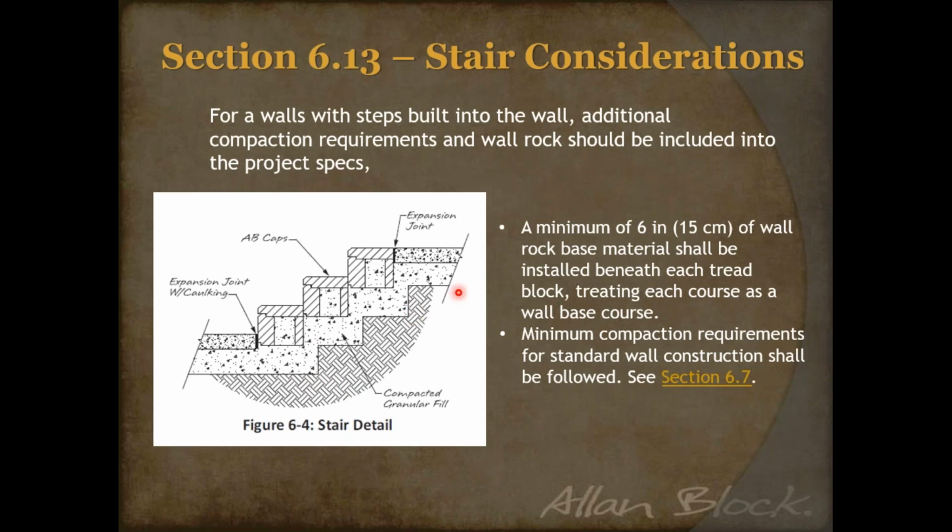In fact, Rich and the guys next month are going to talk about grid. I even recommend putting a little bit of grid in this area because now that holds that entire stair area together. I call it more of a staircase instead of stair steps. That way we're compacting this and it holds it all together. And that's really what we're doing, making sure we've got at least 6 inches of rock underneath this, the more the better, making sure it's compacted to the same requirements that everything else is.